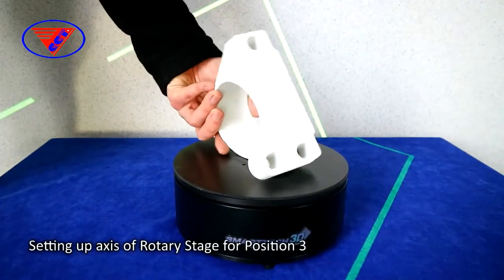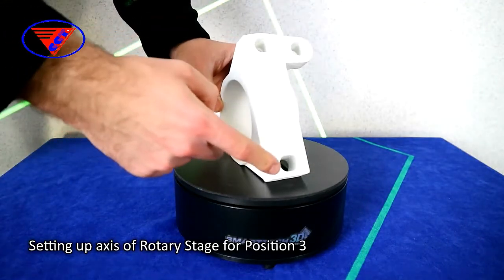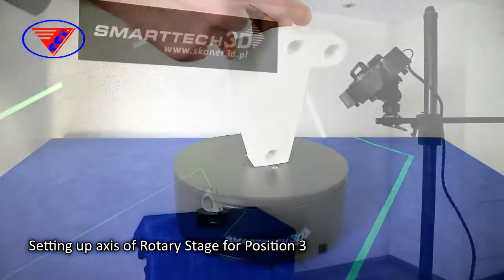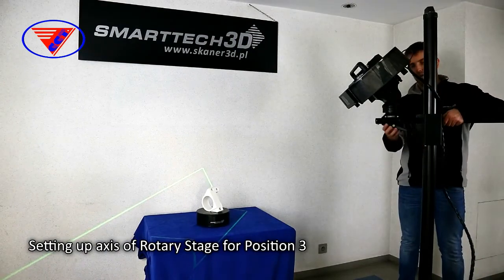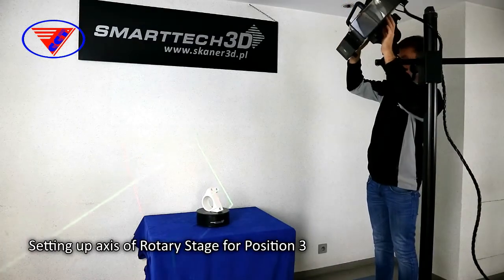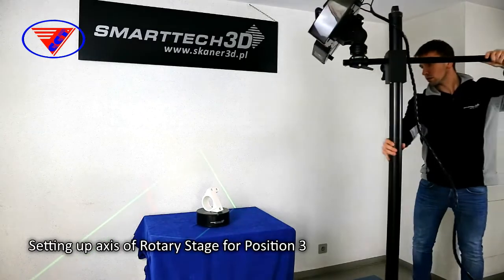For the scanning in third position, we want to capture the edge between bottom surface and perpendicular surface presented on the video. For scanning process, we have to change the position of the scanner and the angle of the scanner to the object. Because we changed the position of the scanner, the calculation of the axis has to be repeated.